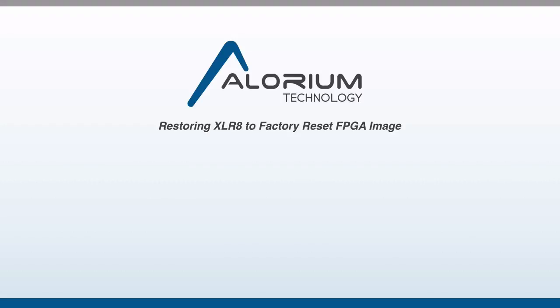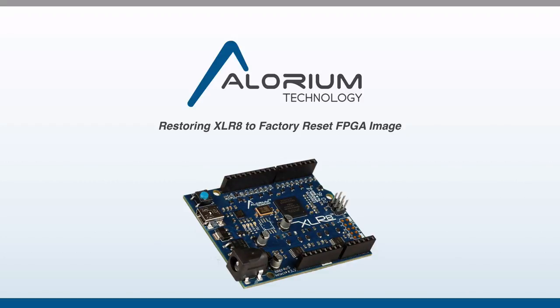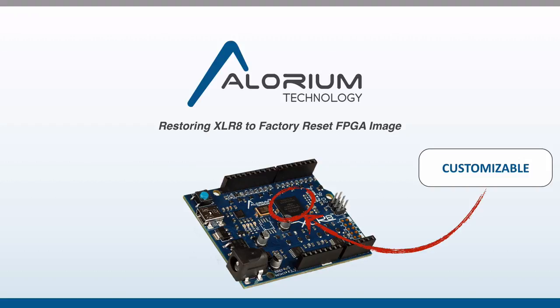One of the features that makes Accelerate so unique is the ability to configure the FPGA with your own hardware functionality in the form of custom accelerator blocks using our Open Accelerate methodology. Providing this level of access gives a lot of power and flexibility to our users, but it also opens the door to the possibility of creating and uploading an FPGA image that makes Accelerate incompatible with the Arduino IDE and unable to load new sketches or a different FPGA image. If this describes you, or you've done this, don't despair. We have you covered. And this video is going to show you how you can get your Accelerate board back to a known good state.